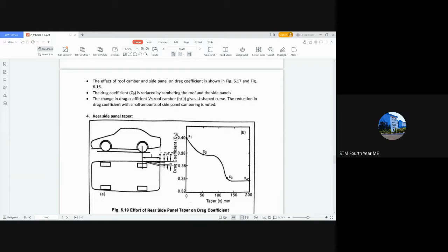Due to the vacuum formed here, a higher pressure region is always present at the nose of the vehicle, and due to the pressure difference, movement from high to low pressure, drag will occur on the vehicle. Such a drag occurring behind the vehicle is known as base drag.